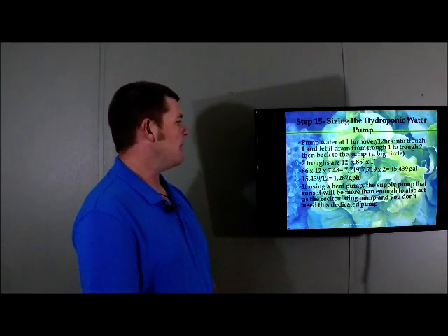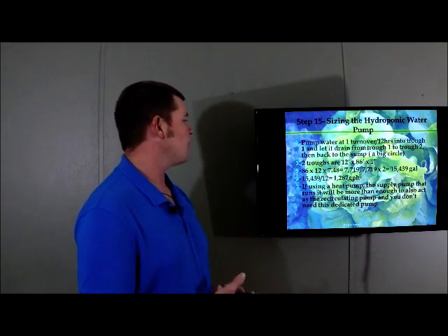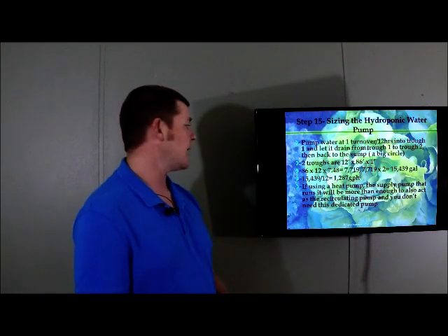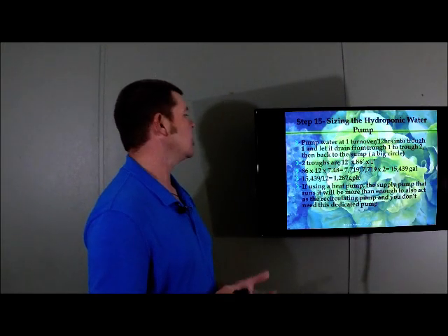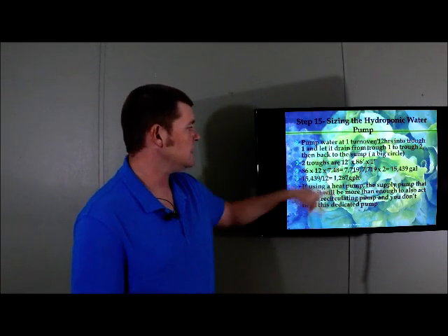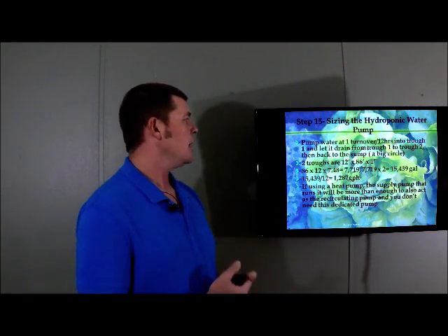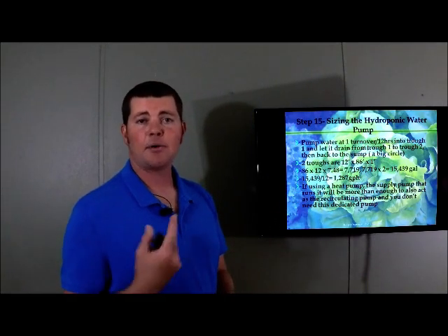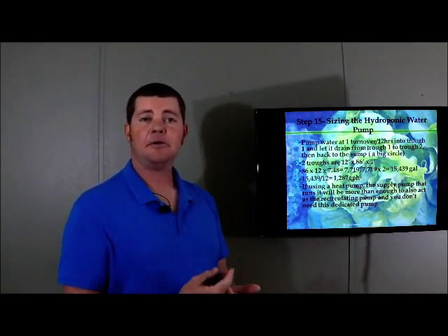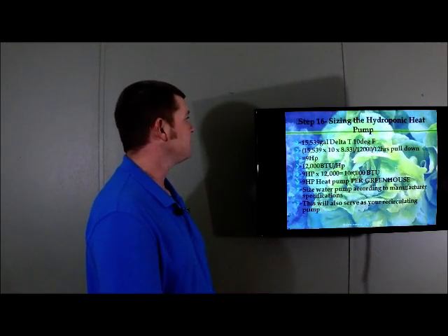If using a heat pump, which we will be in this application, the supply pump that runs the heat pump will be higher than that flow rate, okay? So it'll be more than enough to also act as a recirculating pump within the system, and you don't need to include a dedicated pump. So we don't need to size one off of one cycle per 12 hours, because the heat pump flow rate is going to be more than that, and that's what we'll use to recirculate the system.